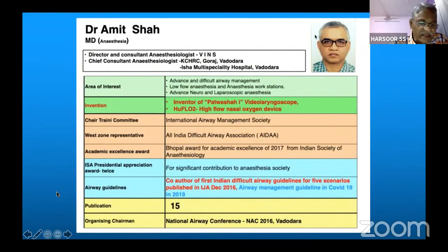That is ventilation. It includes the air handling units, the filtration, HEPA filters, what the temperature is, how many air exchanges should be there, and also the positive pressure and negative pressure. I think a lot of interest was generated during the COVID pandemic about the negative pressure OTs.